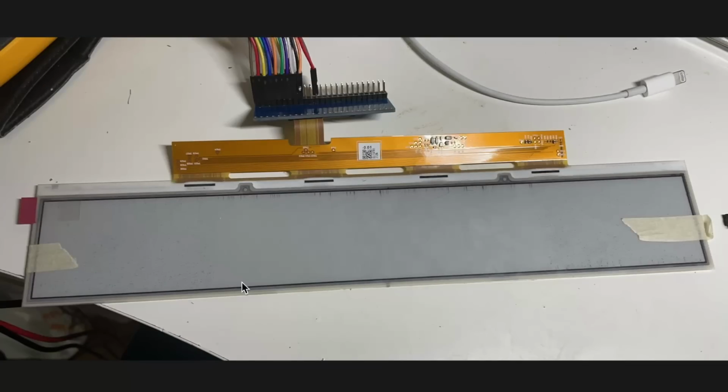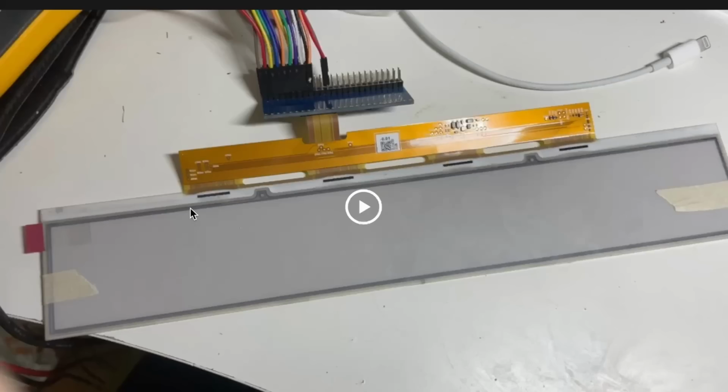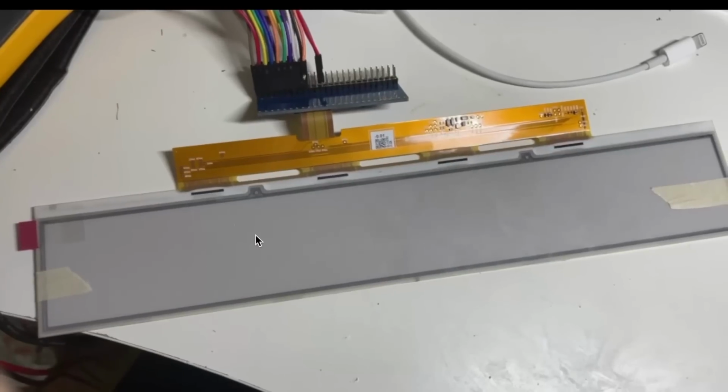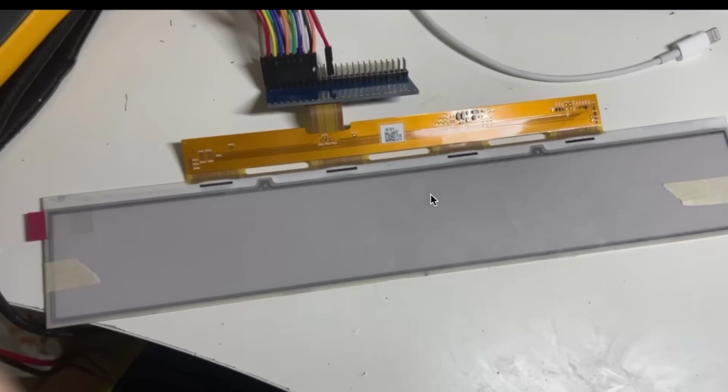I didn't record it because I wasn't expecting it to work, so I have to show you some of the photos I took afterwards. This is showing what happens after I load a LUT or the waveform, and we can see it already starts showing things. There are some weird dots on the side and weird lines in the middle. One thing I can do is use 0x00 and 0xFF, alternating between them, and yes, I got full white and full black. That's looking good.